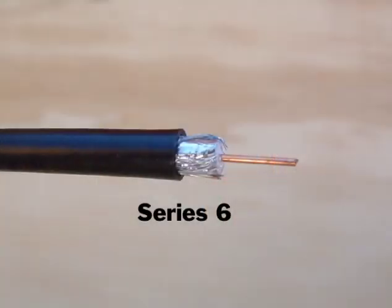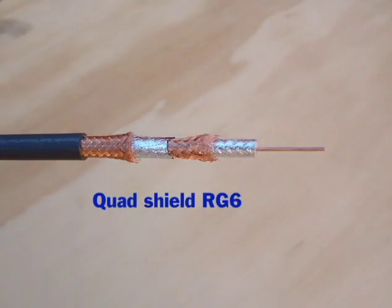By far the most common coax cable for residential use, recommended by TIA 570, is Series 6. The most common designation for Series 6 cable is RG6. RG6 offers a good combination of size, cost, and low-loss performance for the distances typically found in homes, and it'll be your cable of choice for residential installations.